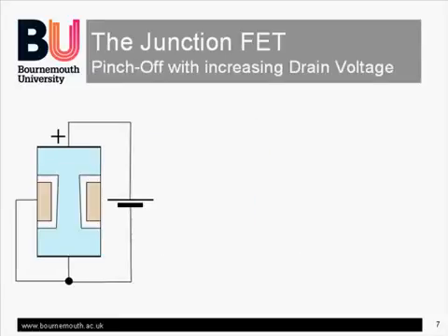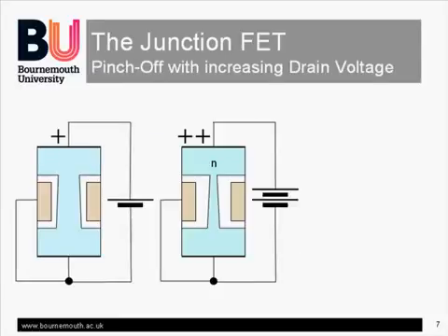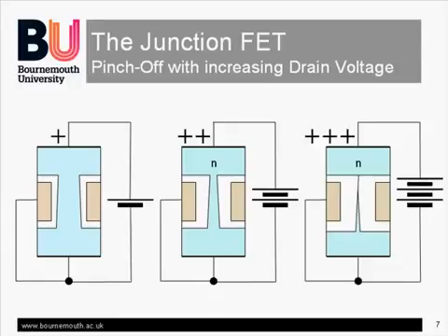When the drain voltage is increased, the depletion layer grows and will pinch off the channel at the drain end. However, it can't entirely close the channel because the reverse bias is itself dependent on the channel potential gradient set up by the drain current flowing through it. What will happen is that the pinch-off will simply prevent an increasing drain voltage from producing any further rise in drain current. It effectively insulates the drain current from any change in the drain voltage.